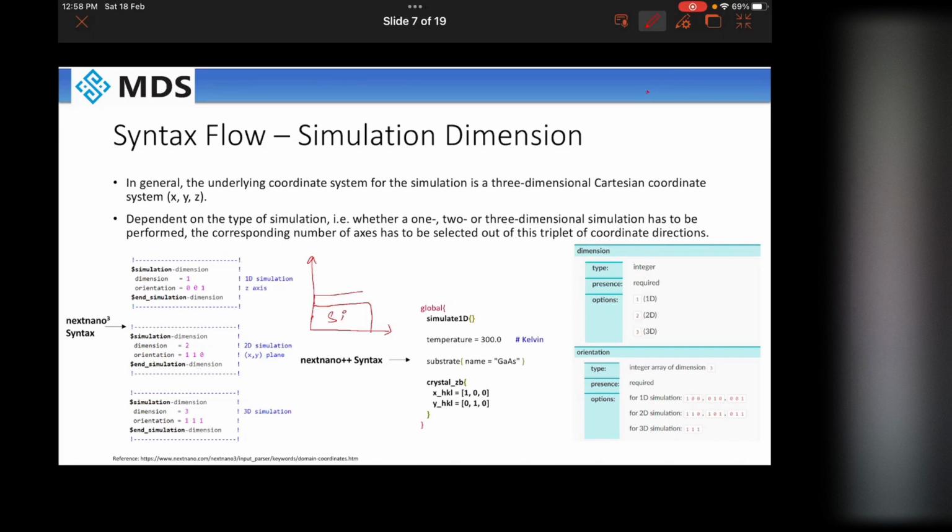Then you have multiple layers. You have grown the multiple layers using molecular beam epitaxy or any other instrument, like maybe GaN, AlGaN, multiple layers. Now, if you simulate in 2D, your contacts will be either on the top or the bottom side, or maybe this side. So the core structure is this part.